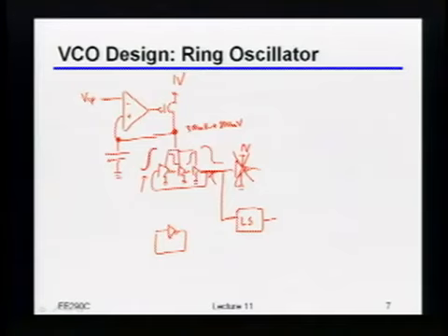And again, this is one of those places where people don't necessarily spend a whole ton of time, and we won't spend too much time talking about it today, but be careful, because especially if you've got this wide range of voltage at the input, you can get all kinds of nastiness happening in that level shifter. Just as an example, what are a couple ways you could build that thing? I'm sure you've seen these before. What are a couple ways you can build that level shifter?